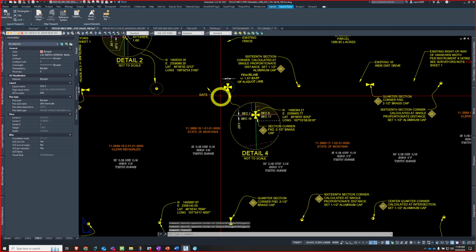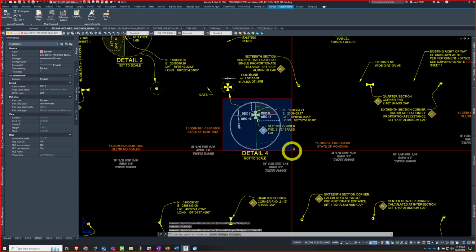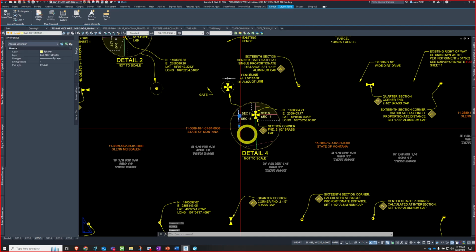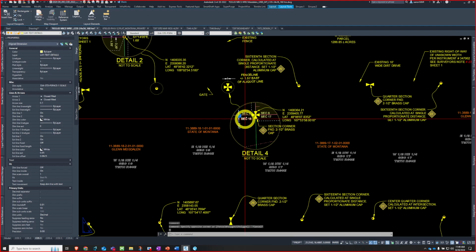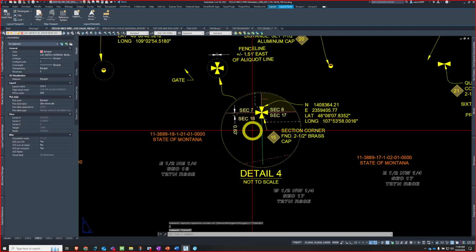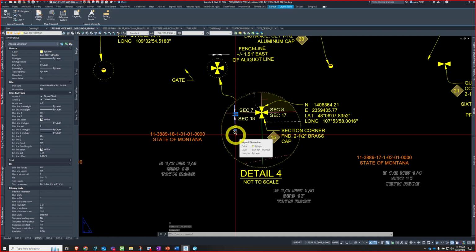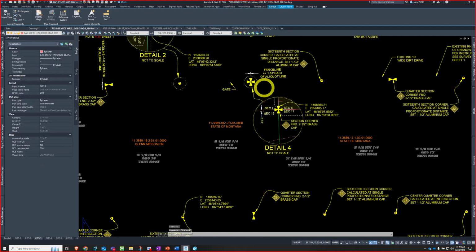With details like these, putting them in paper space with a new viewport layer was a good way to go. Then inside of these viewports, having unique layers that don't plot so you can do annotations was helpful. But once in a while, you can't get everything perfect and you just have to pick a method. I did some of these annotations in paper space for these details, instead of putting them in model space on a unique layer, because I want them to show here but not on the overall layout.